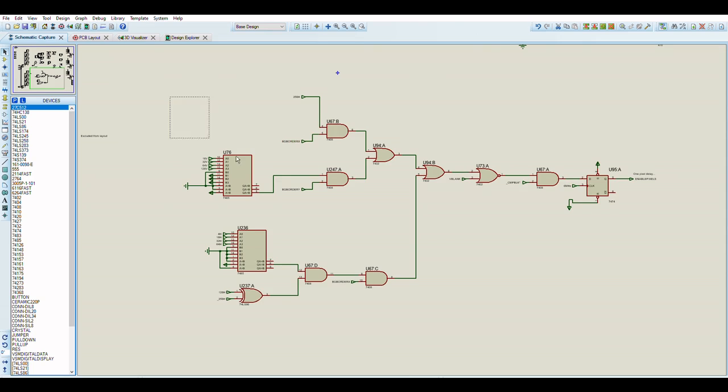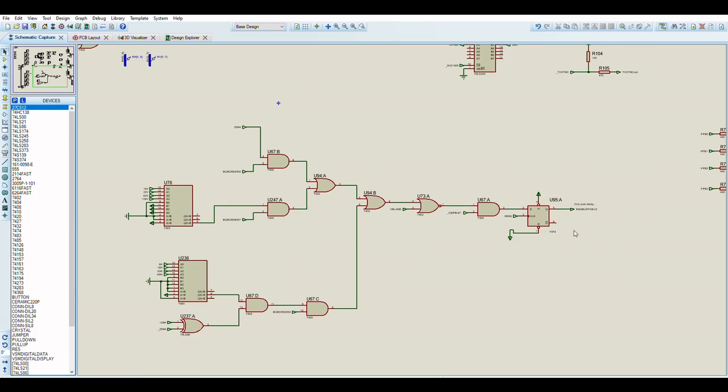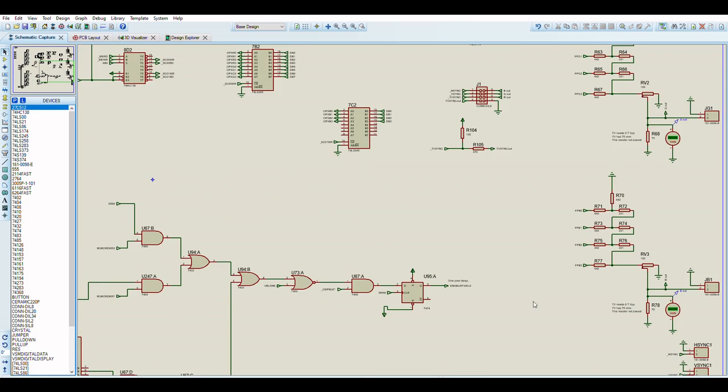And it takes all of these values and comparison results and border flags and the V blank and whether or not it's doing a compare block and so on and so forth. And then it basically decides whether or not we are going to be outputting pixels with 1 pixel delay, because we're using a flip-flop and we're clocking it on the 6 MHz clock.